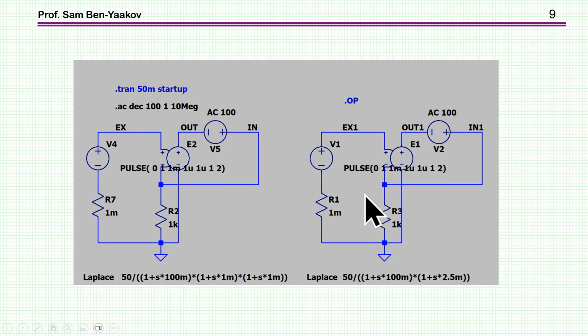So to demonstrate this whole issue, I've set up an LTspice schematic. There are two parts to it. It is a feedback system in which I'm describing the system by a Laplace transform expression. This is the expression, and LTspice accepts it, so I can run a time domain and a frequency domain analysis, that is, AC and transient analysis.